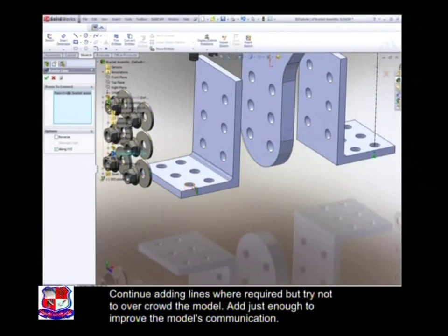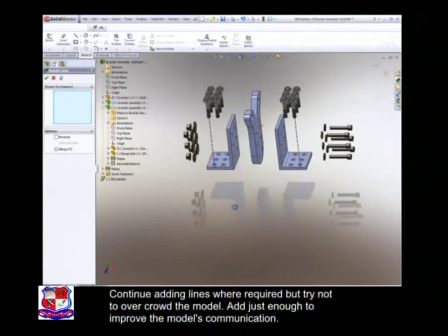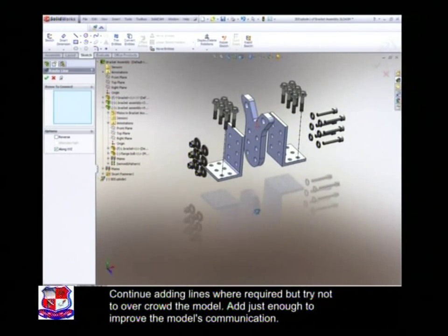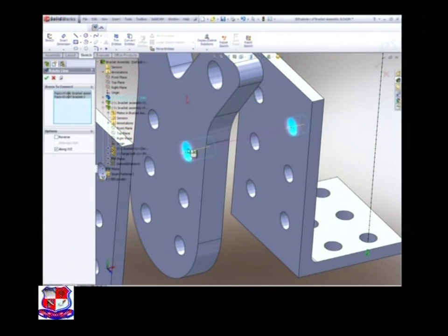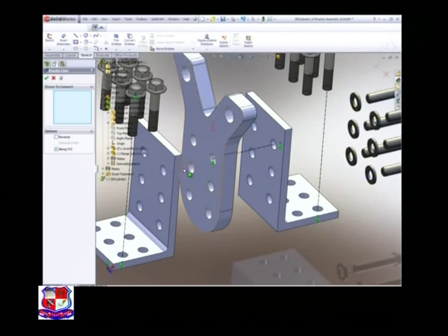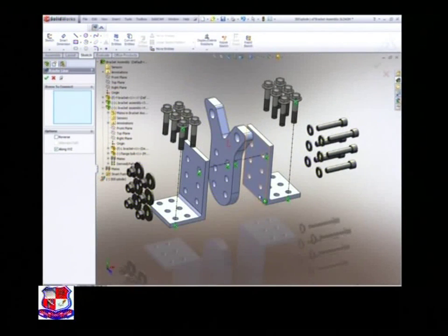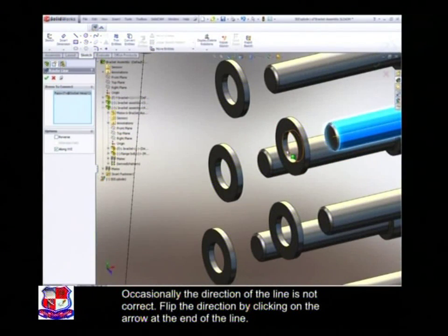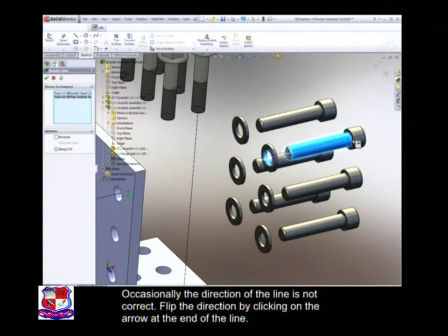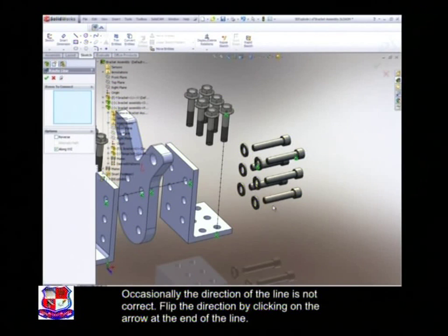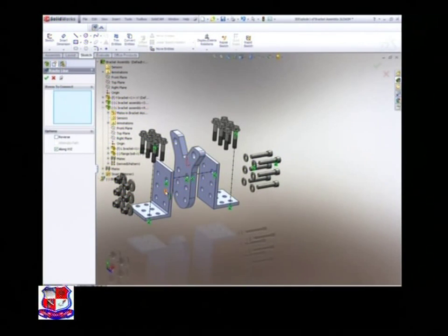So let me select this one. Similarly on this side also, the shoulder of this nut and this hole are selected over here. This hole, select that. These two holes are collinear to restrict the movement. These two holes are also made collinear, and this side also, this nut which we have selected with this washer inner surface are made collinear, and this surface, this one, select that surface. Now all these points are selected,